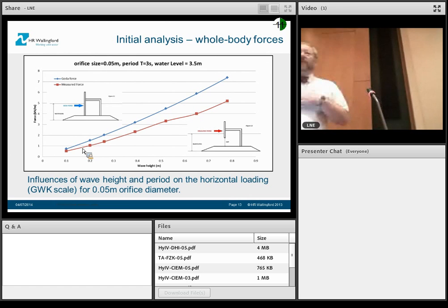So, for the boring engineers amongst us, what we want to do is, we want to say, what is the total whole body load on the caisson? Because the emphasis in many places is to build these remote, away from the land, so we have to resist the sliding load. We'll pretend that we can use Professor Yoshimi Goda's method for forces, and then we imagine that we apportion some of the load on the front hood and some on the back.